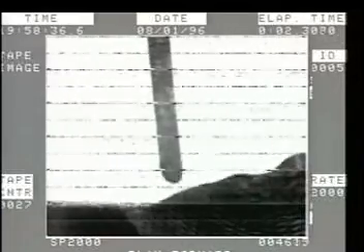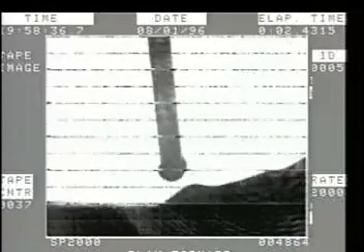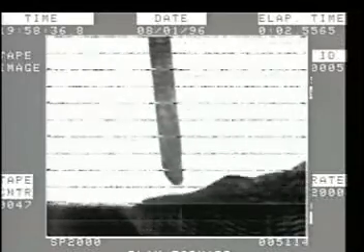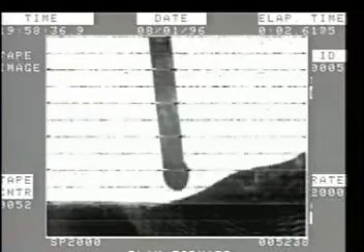Here is a close-up of the short-circuiting process. There's some spatter, a little bit of violence associated with the arc. The crisp buzzing sound is caused by periodic short circuits. By using high-speed photography, you can actually see droplets forming on the end of the electrode. Current is applied, the droplet pinched off, and transferred into the puddle.